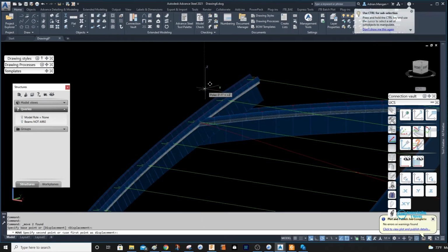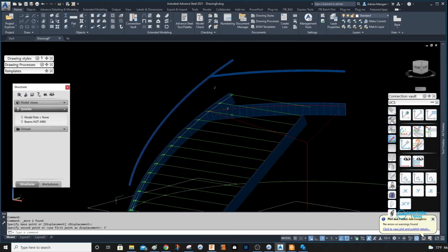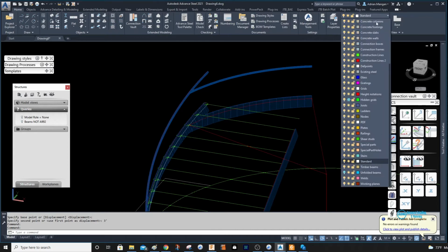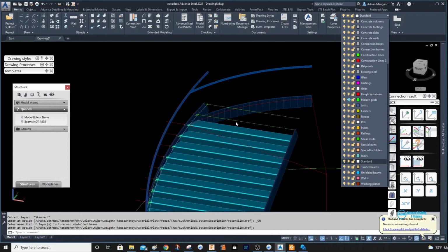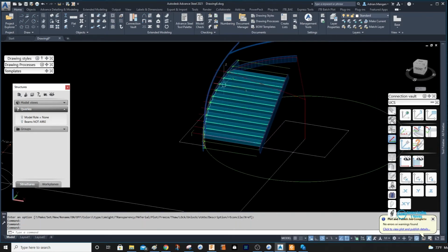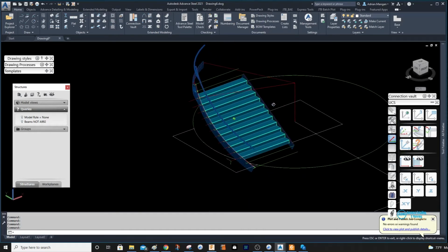And for a handrail, it's probably going to be up 2'10" or 3 feet. I like to do 3 feet just so I'm not too low. And that's kind of where you're at. I hope that helps. It's not perfect, obviously, but it kind of gives you an idea of where to go and what to do when you're doing this type of stairs.